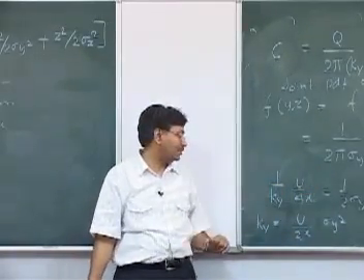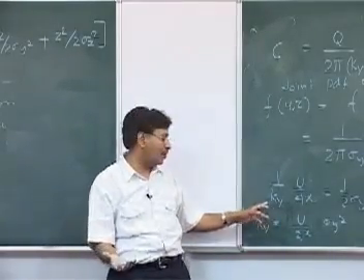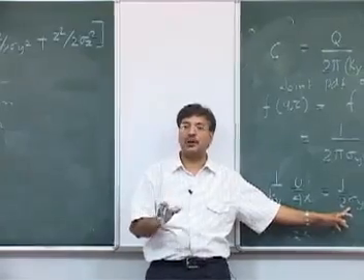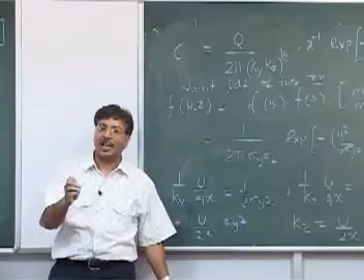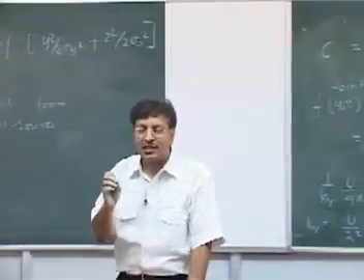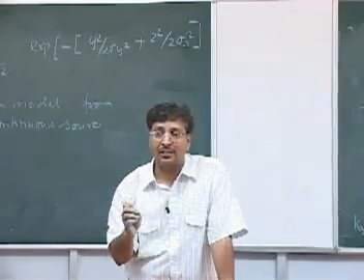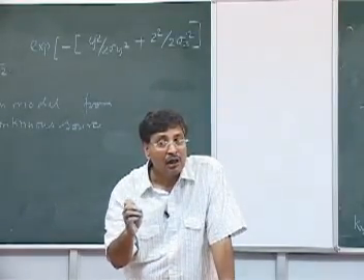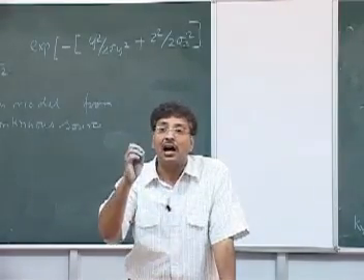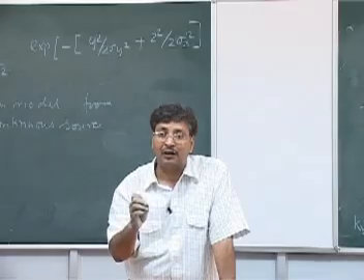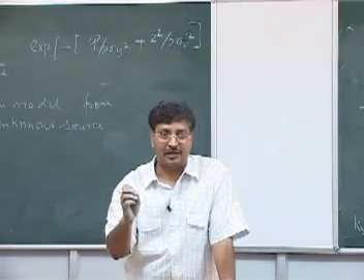And similarly my dispersion is lost. Where has it gone, my dispersion? It is in some formation of sigma y and sigma z. So that we'll see. So before we end the class, sigma y and sigma z will be function of x and ky and kz, and ky and kz are function of turbulence, right?